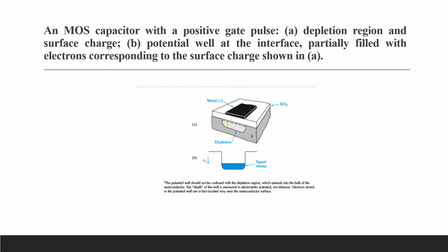What is needed here? A simple method for allowing charge to flow from one potential well to an adjacent one quickly and without losing much charge in this process. If this is accomplished, we can inject, move and collect packets of charge dynamically for a variety of electronic functions.